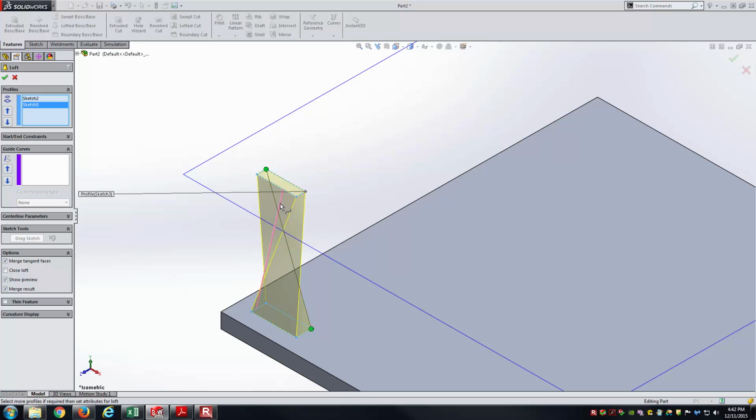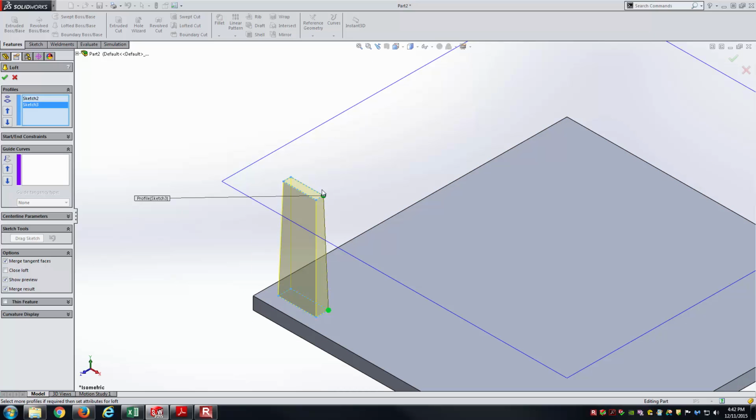The reason I picked those similar regions is because I want these connectors to follow the same vertices. Notice here, without getting too much into the lofts, depending on where that second vertex is landing, I'm getting slightly different geometry there. And so here I want a nice linear translation between these, and so that's where I'm making sure to select the same points, if you will, or close to the same points. That way it picks up the same points for those connectors.